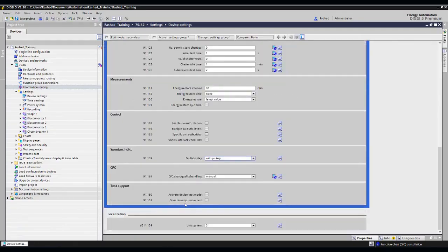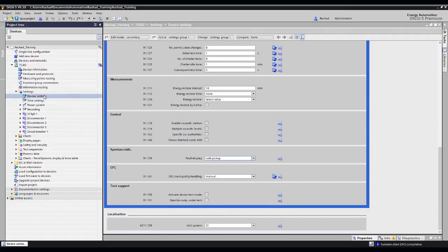All right? Whether you entered it through this method or that method, the idea is when you put a relay in test mode and come to test, I tell you here that the binary output, for example, might not be working. Why? Because it asks you whether to allow the binary output to operate under test mode or not. So if you haven't checked this part, nothing will show up, and I'll leave it unchecked for now so we can see its effect later on. All right, so we've talked about our device setting.